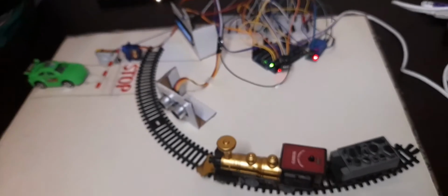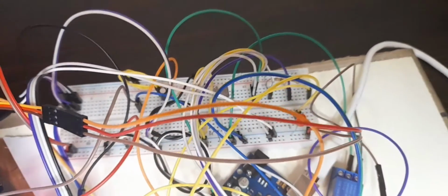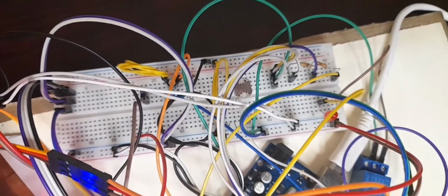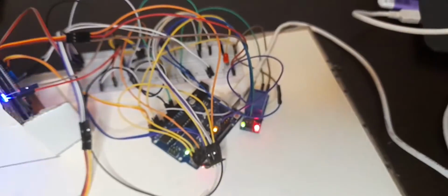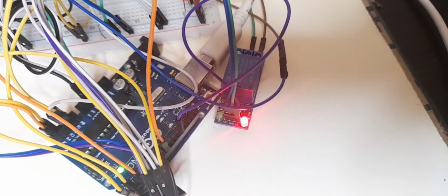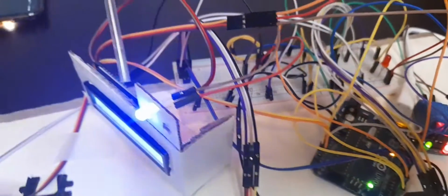I have also used the LDR, which is just here on my breadboard, which can function as a light or darkness sensor, but for my project I've used it to detect darkness, such that in dark instances it will be triggered, and I have coupled the sensor with the relay over here, and when the relay energizes, the LED will flash on, providing adequate lighting on the entire crossing.